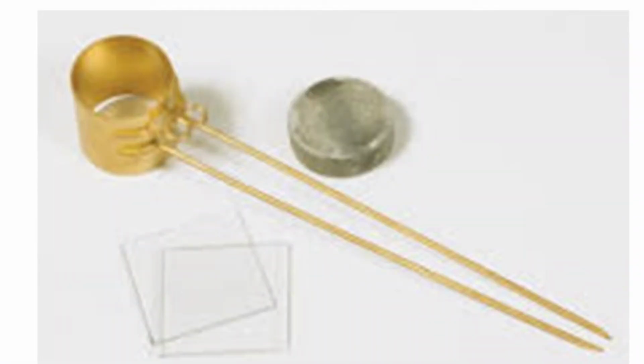The soundness test is done with the Le Chatelier apparatus. There we place the cement in a mold, which I am showing you, and we note the reading between the two needles. After heating it and cooling it for 24 hours, we again read the reading between the two indicator needles.